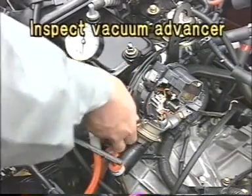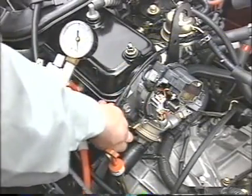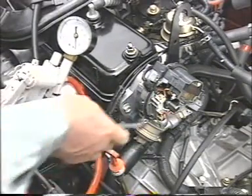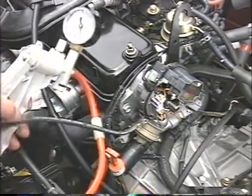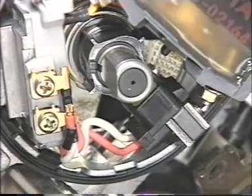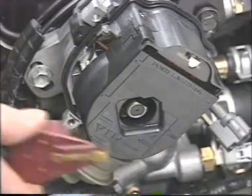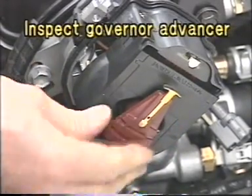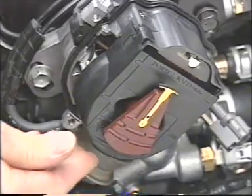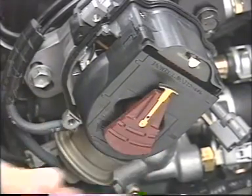To inspect the vacuum advancer, disconnect the vacuum hose and connect a vacuum pump to the diaphragm. Apply a vacuum and check that the vacuum advancer operates correctly. When inspecting the governor advancer, turn the rotor forward, release it, and check that the rotor quickly rotates backward. And check that the rotor doesn't rattle.